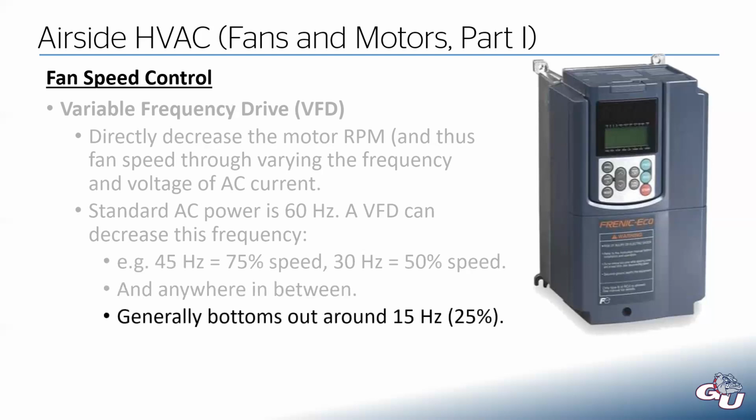Well, as long as we don't go too low. Right around 15 hertz or 25%, that is generally the low limit. And you start running into some operational issues if you keep trying to push that VFD to a lower speed.